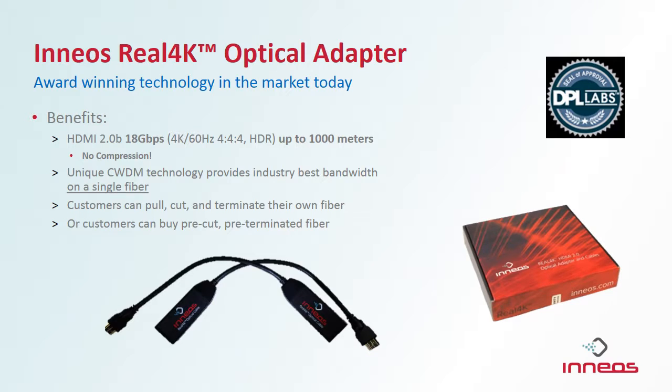INEOS has two types of real 4K products, an optical adapter and an optical extender. The optical adapter supports HDMI 2.0b, 18 gigabits per second, with any type of HDR up to 1,000 meters, no compression, using our unique CWDM technology, so that all HDMI and CEC is done over one single fiber. So this allows customers to just pull standard fiber in the wall, come terminate it on their own, and plug in the optical adapters when it's time to do the installation. Or if you're not comfortable terminating fiber in the field, you can buy pre-cut, pre-terminated fiber and pull that as well.